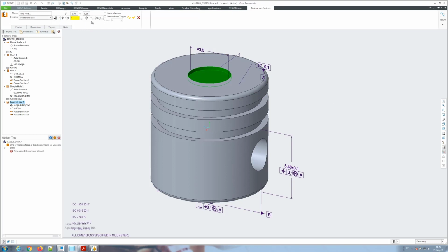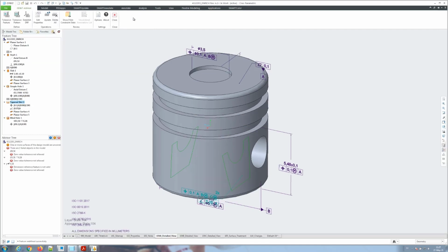I get some input from the system. The GD&T Advisor thinks that a position tolerance could be suitable. You need to define the value for it. We need to set the references, and whether you want to have the material conditions or not based on this. And the system also automatically identifies references for the whole diameter and the whole depth. So if I accept this, okay,